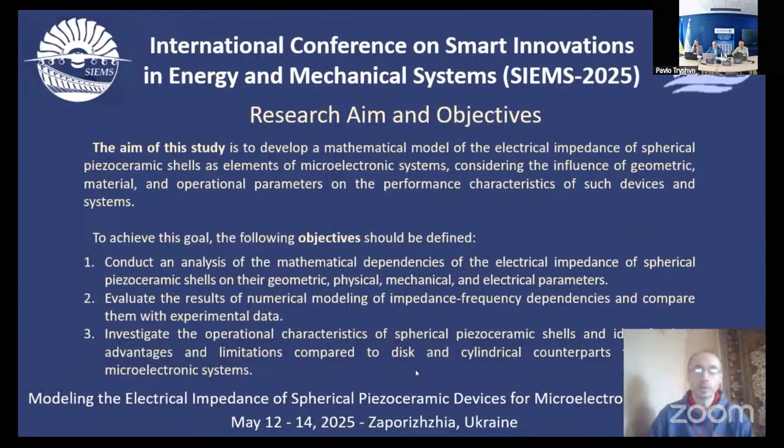To achieve this goal, the work solves three key tasks. Analytical analysis of the dependencies of electrical impedance on geometric, material, and electrical parameters of spherical shells is performed. Numerical modeling of impedance frequency characteristics is carried out with further comparison with experimental data. The functional features of the operation of spherical piezoceramic elements are investigated, and their advantages and limitations in comparison with disc and cylindrical analogs for use in sensory, diagnostic, and energy microdevices are substantiated. Thus, the presented research is aimed not only at formalizing the theoretical model, but also at its practical application in conditions close to real operation.